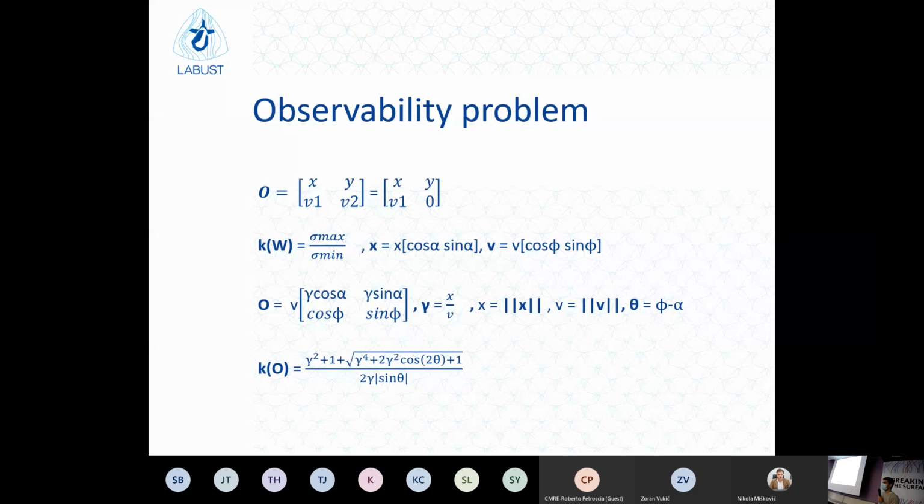So then, because the frequency is so low, we need to ensure that every measurement that we get is observable. Observable basically means that every time you get a measurement, you can reconstruct a state vector from it. In that state vector, you have position, pose plus speeds. So it turns out that this is the observability matrix.